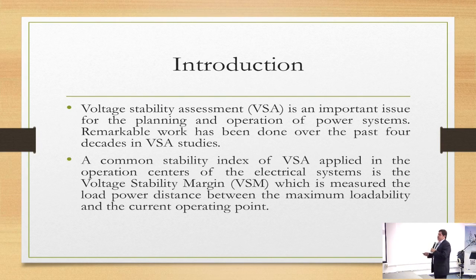So if an operator knows precisely the direction of load and generation growth, then the voltage stability margin is of practical significance. However, if there is too much uncertainty on this information, then you may get a poorly reliable voltage stability margin.